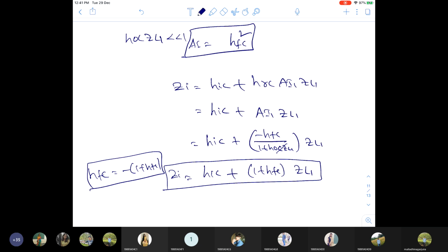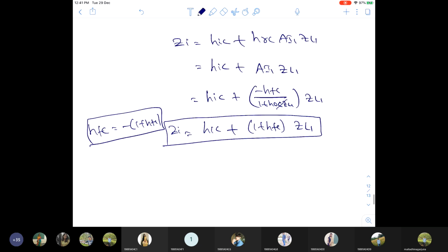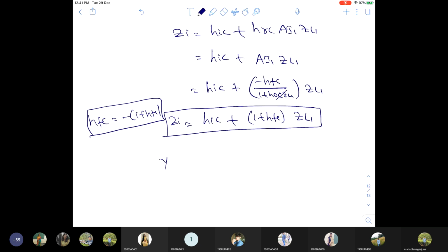Okay. So now the remaining you can calculate, and Z naught 2 is equal to 1 by Y naught 2. That is the same term. Okay. So what are we doing all these things for? This Darlington pair is meant to improve the input impedance. Now let us verify whether the input impedance is increased or not.